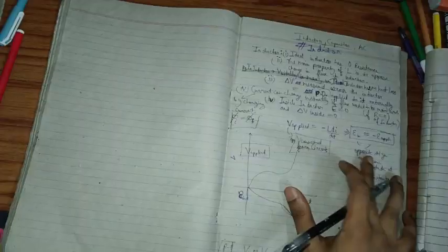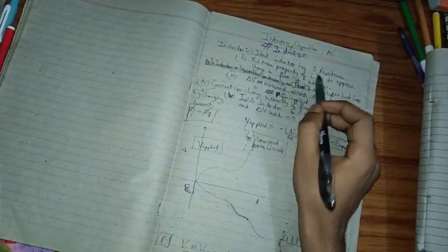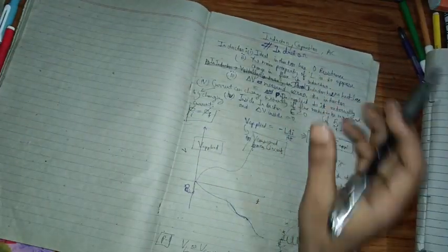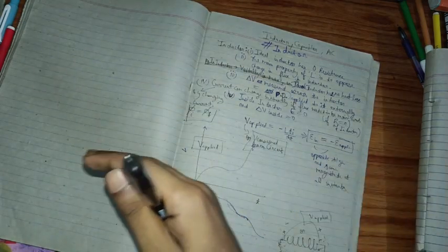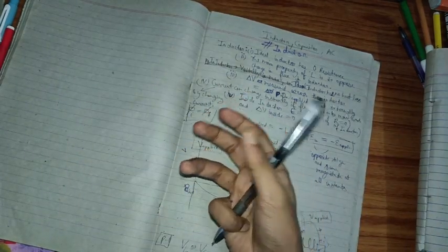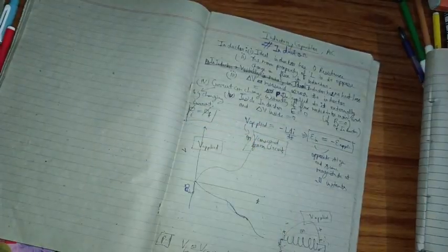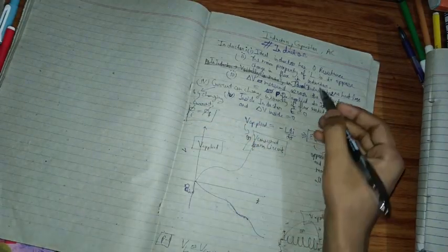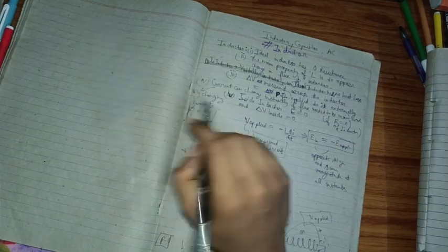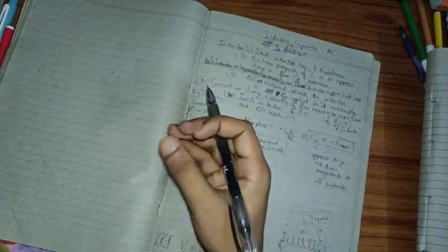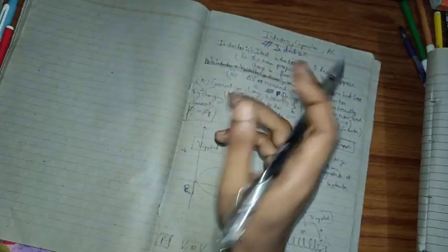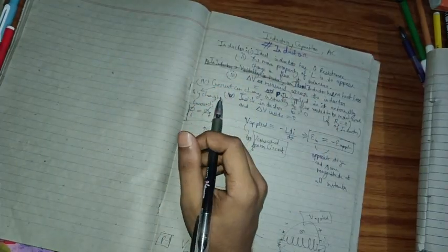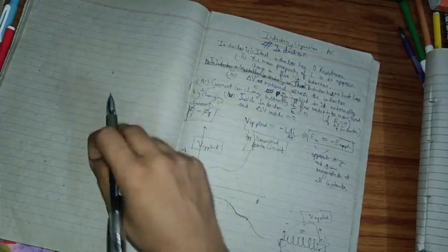But if the permeability of the medium is fixed, then the flux can only be changed by the change in current in general. So that's why, to oppose the flux, the current is also opposed to change. And an ideal inductor has no heat loss, and delta V measured across the inductor is equal to the potential difference applied to it externally.